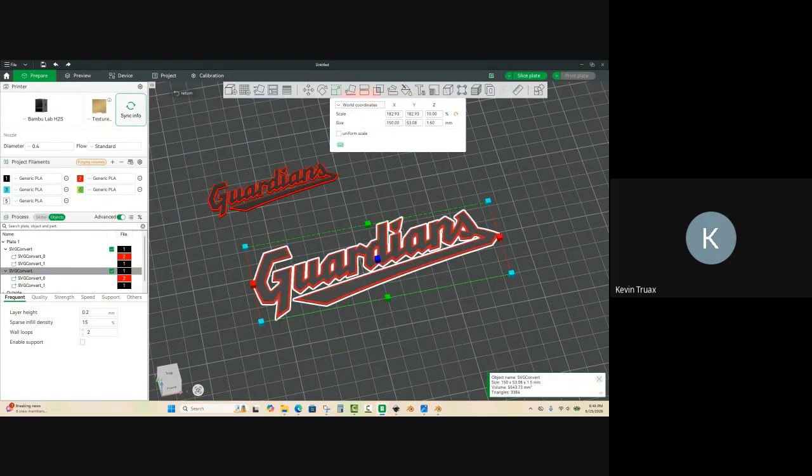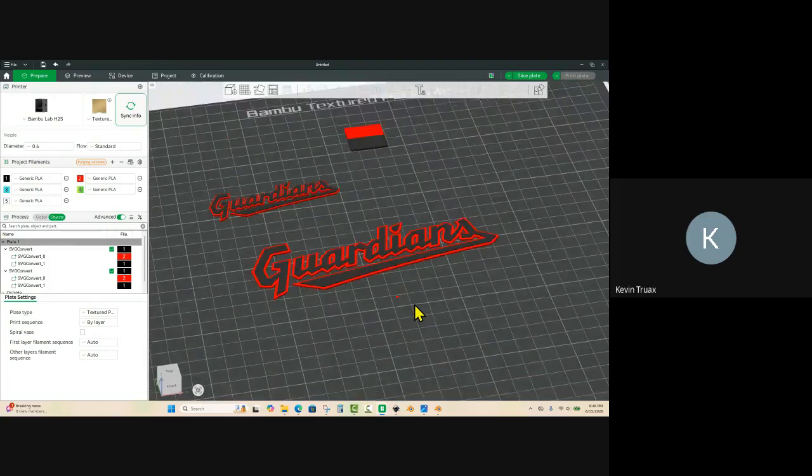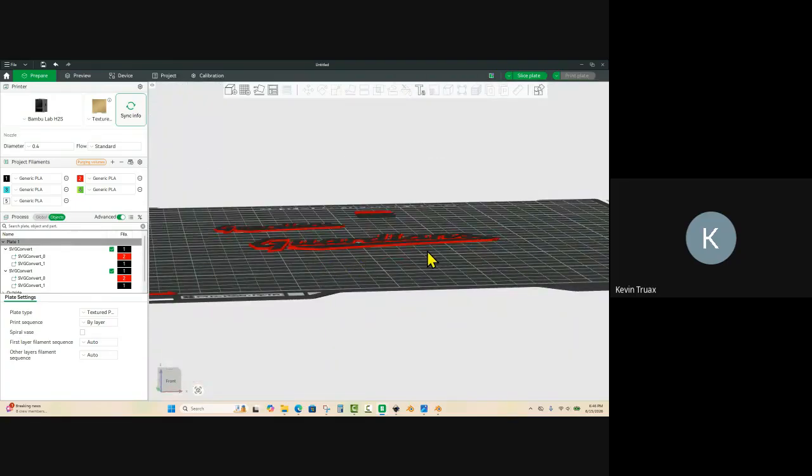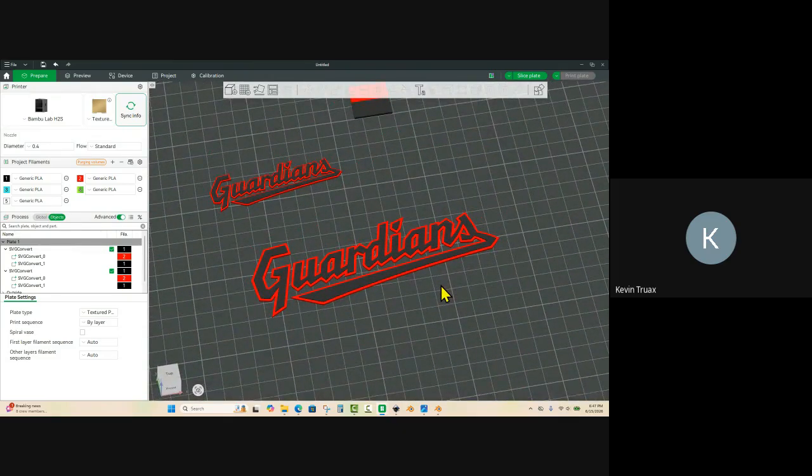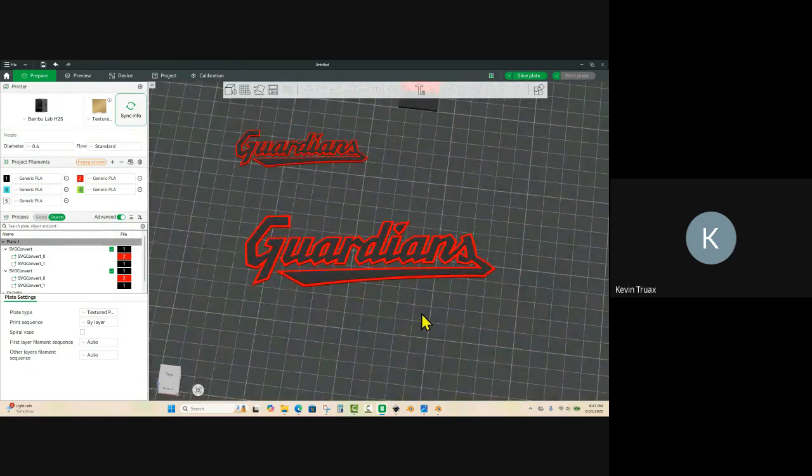So when we do it that way, our logo proportionally does not change. It looks exactly the same. But the thickness remains the same thickness, right? It's only 1.5 millimeters thick. So we'll be able to bend it real easily to fit our lampshade. We just warm it up a little bit, and we can bend it to the contour of the lampshade. So when we want to scale things up without changing the thickness, that's how we have to do it. We scale it, find out what that magic number is supposed to be, then we back step and redo it manually, and you'll have it.